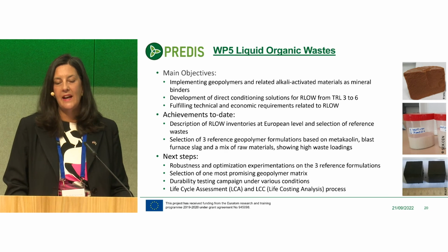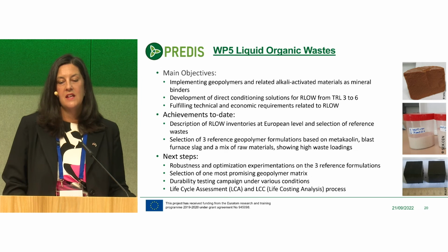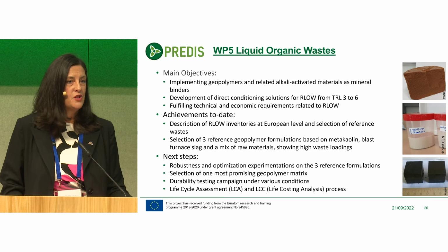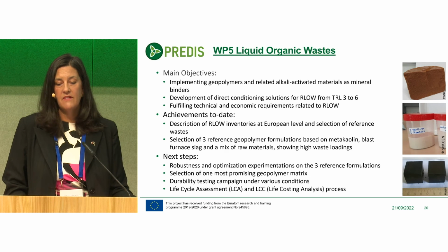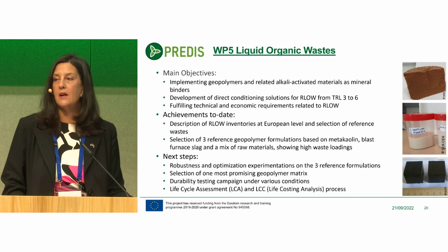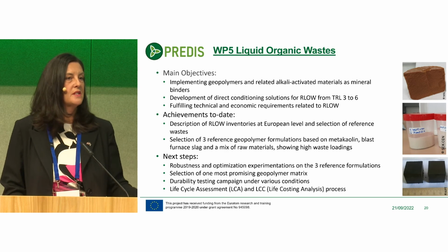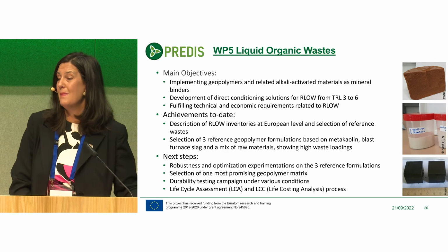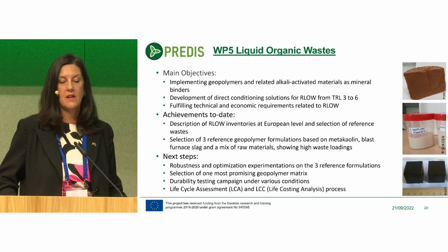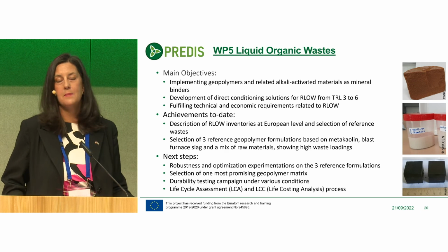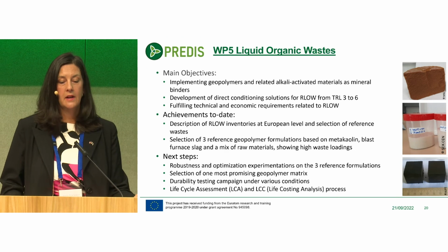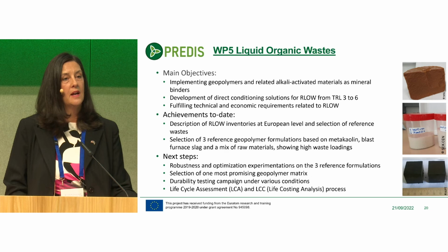And again, really looking at what are the ways to condition these materials, looking at alkali activated materials and geopolymers, understanding what are the challenges in the inventory, coming often from the plant operations, and looking at new types of formulations with geopolymers, with metakaolin, with slags, trying to reduce this environmental burden, avoid using cements if we can, and optimizing what types of materials we should use in treatment and making sure that if we do invest in these new types of materials, that they would be acceptable by a repository and a regulator in the durability and the lifetime in the safety case.